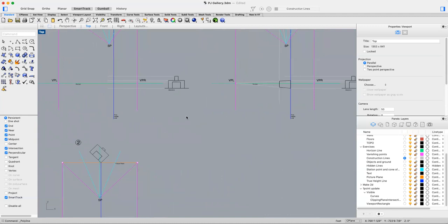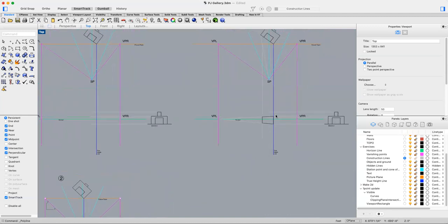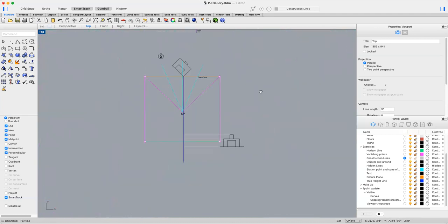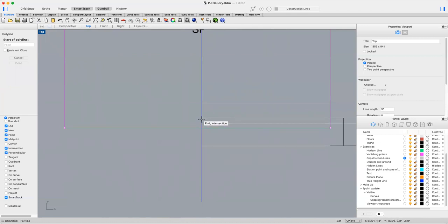So now where are we at? Now we're ready to draw our first face. So we're going to do that by, we know this corner is on the true height line, and we know the height of that corner. So it's from that point to that point, top and bottom, and we know it vanishes in the 2 directions. So let's go ahead and set that up.